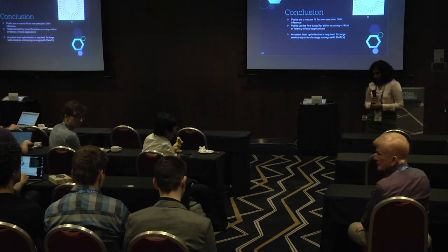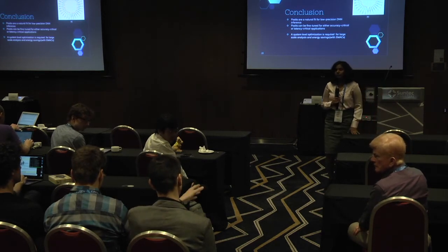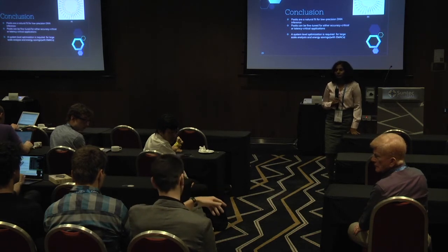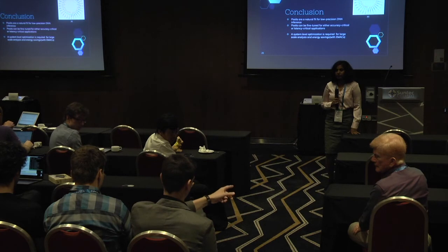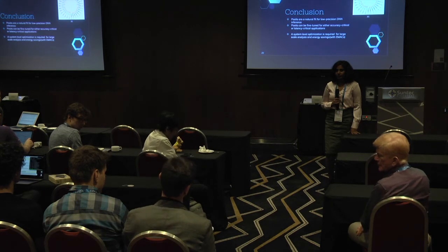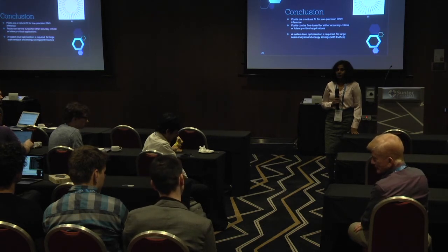So what you're saying is that even if you have conversion functions, posit to internal format, operation on the quire accumulator, and then internal format to posit, you consume less than a 32-bit floating point unit, having the same output precision?